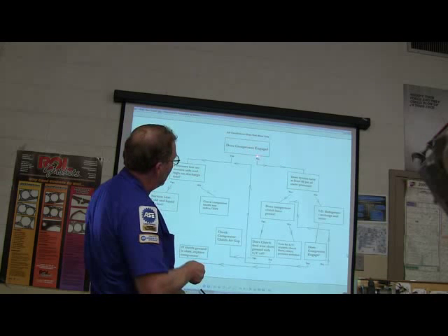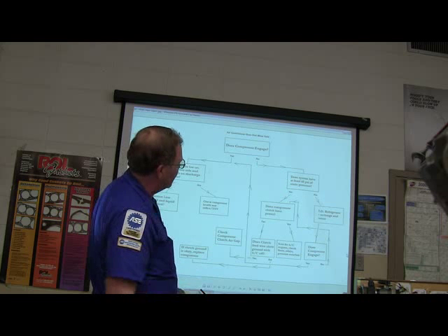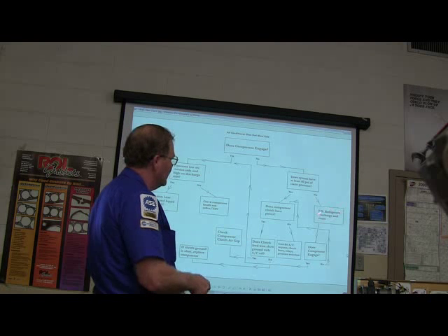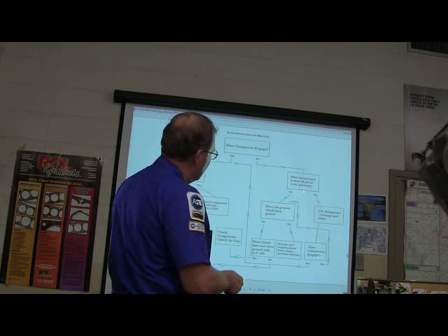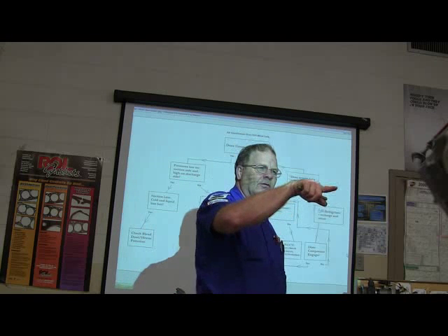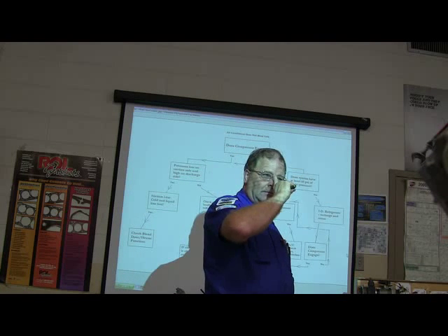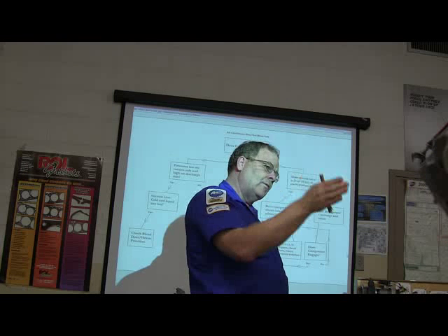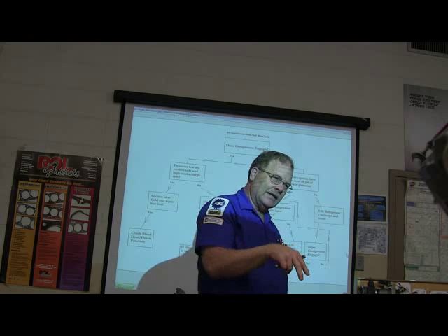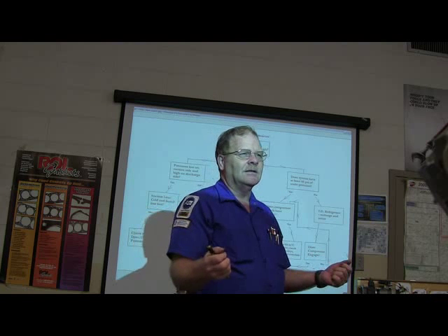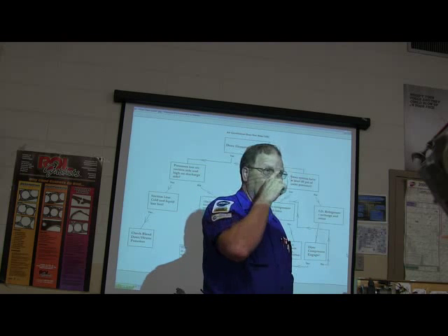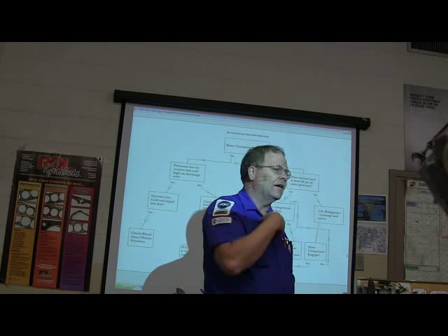Quincy, if you discuss no, does the system have at least 60 psi of static pressure? See, that's why I say at least 60. If it doesn't, you're going to add refrigerant, recharge and retest. If it does have 60 psi, I want to know, does the clutch have power? Did the clutch have power on the one that you worked on, Moody? No, it did not. However, when we jumped past the relay and energized the compressor clutch, it got cold. Everything felt normal, right? What's that tell you? There's no power getting there, and you've got to find out why.